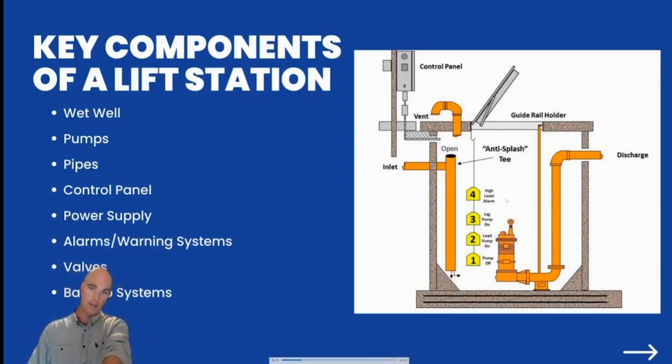So then we have the pipes themselves. So here I've got the inlet pipe. This inlet pipe right here has an elbow that puts it all the way at the bottom. Sometimes the water, if the inlet's low enough, it will just come straight in. In this case, it's coming down an elbow. And then here, another pipe, I've got the discharge piping here. So essentially the pump gives the water into the discharge pipe, and then it goes into its ultimate location.